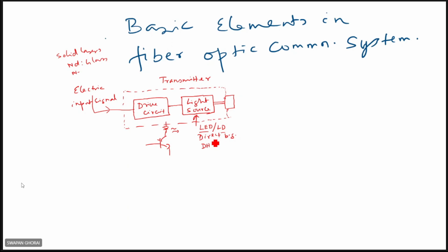direct bandgap type materials. Like say it can be NNP type structures. You see N, N, and P type. Capital N means larger band gap, smaller band gap, larger band gap. Right. Interestingly, you'll see it. Probably you have studied, NN can form junctions in case of heterojunctions.